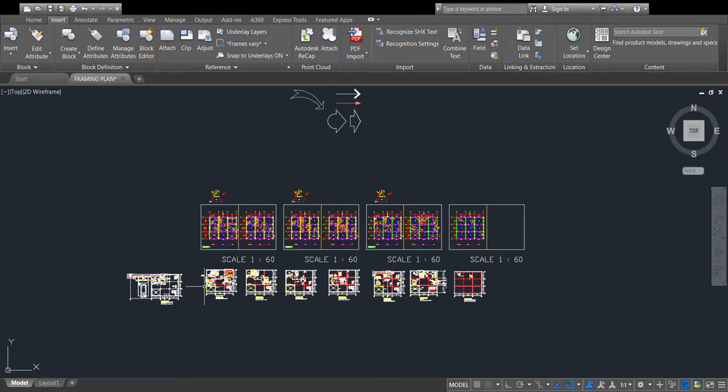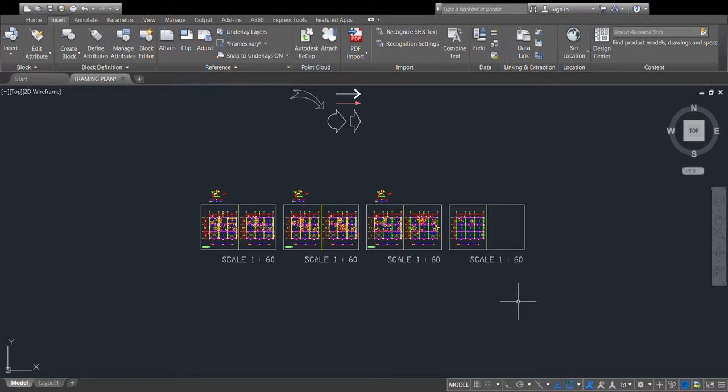The reason is simple because in my project, we are actually using it as a basis in doing our structural plans. So in the meantime, delete it by erasing it. So press E and then Windows select these unnecessary drawings. Press enter. Okay, now you're going to insert your very own drawing. How are you going to do that?